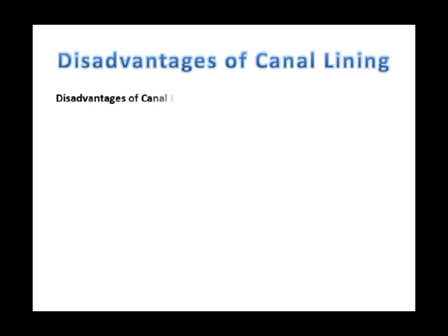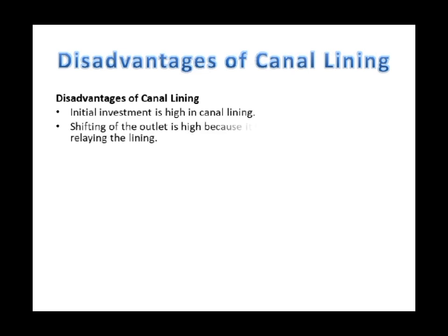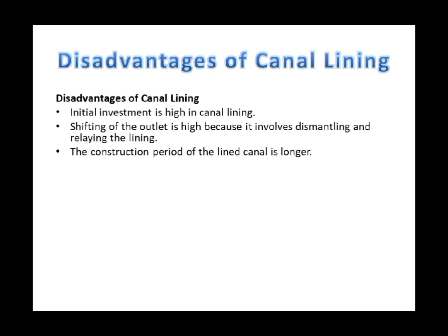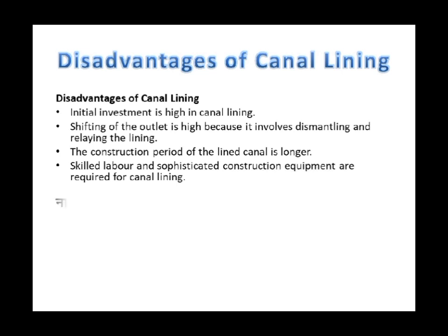Disadvantages of canal lining. Initial investment is high in canal lining. Shifting of the outlet is costly because it involves dismantling and relaying the lining. The construction period of a lined canal is longer. Skilled labor and sophisticated construction equipment are required for canal lining.